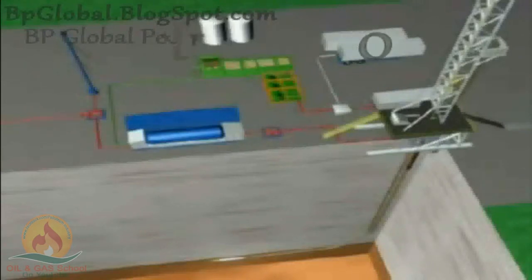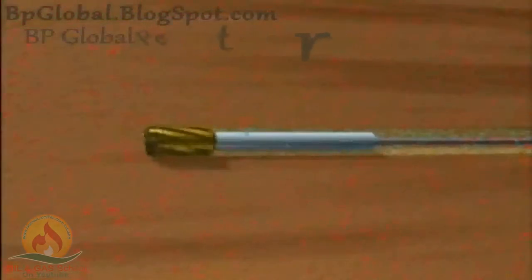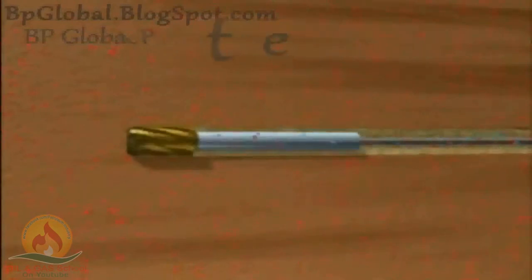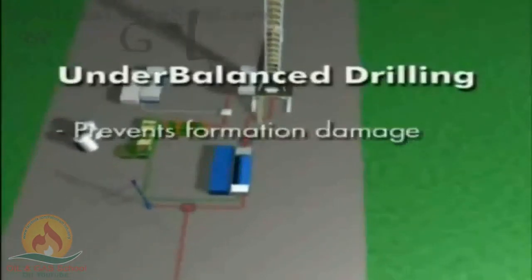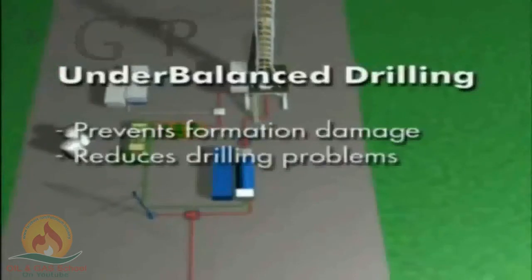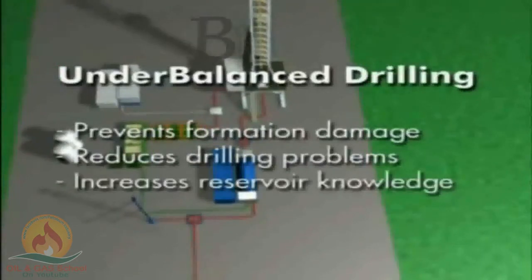The light fluid is pumped back to the rig's mud system for treatment and reuse. This completes the tour of the main surface systems that are used in 2-phase underbalanced drilling operations. In summary, underbalanced drilling allows the well to produce during the drilling phase. Underbalanced operations require additional surface equipment and a careful upfront design. When applied in appropriate wells, underbalanced drilling prevents formation damage, reduces drilling problems, and increases reservoir knowledge.